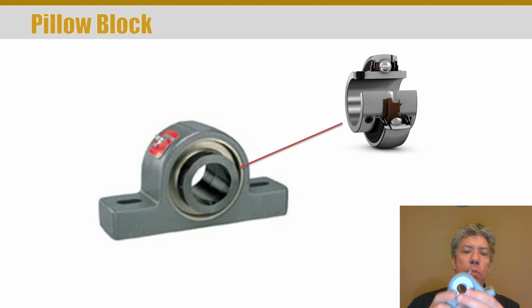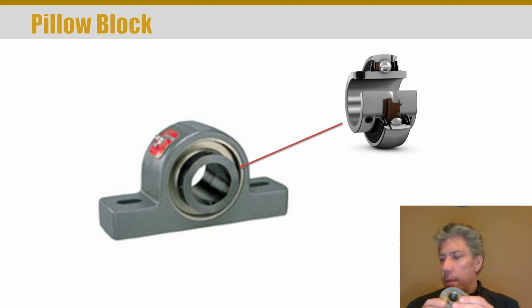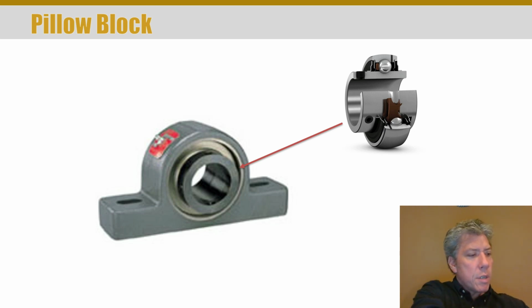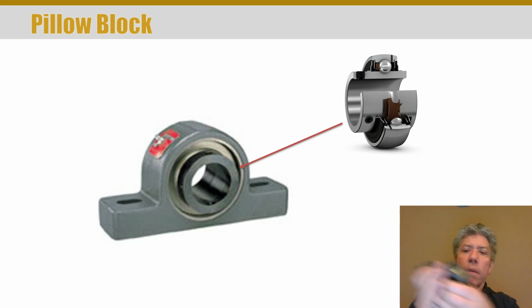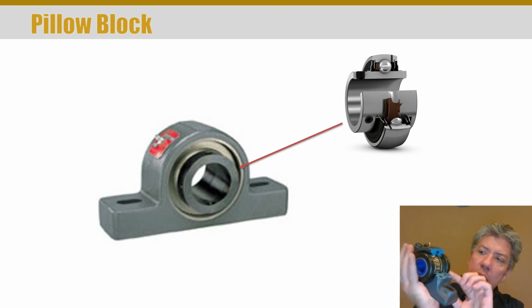So it's actually important that part of your maintenance schedule be to clean that fitting and then insert grease. But there's many different options with these things. I've got some like this really large pillow block bearing, and this one's been cut away so that you can see some of its elements. If you can't see it, I'll describe it.